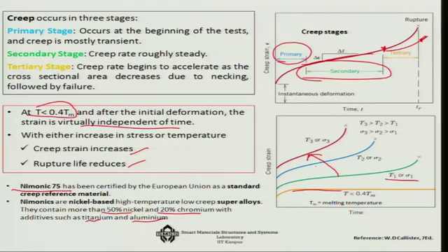And I will not go into the details at this moment, but there are various mechanical models that are used actually. A very common model is something like a spring, a material model, and a dashpot combination in series. Okay. And the load is coming here. So, this is a spring K and this is a dashpot. Okay. So, imagine that you are applying a load F and how this system will be behaving. That is something that approximately simulates the creep behavior of a system.